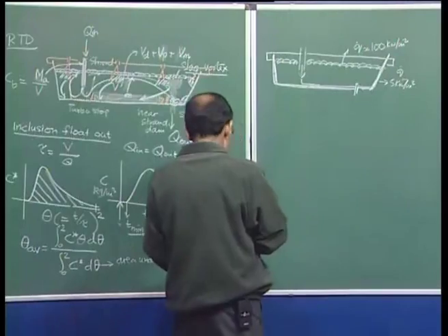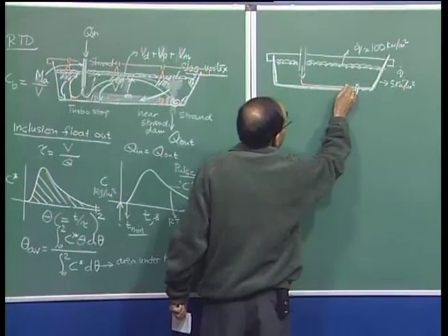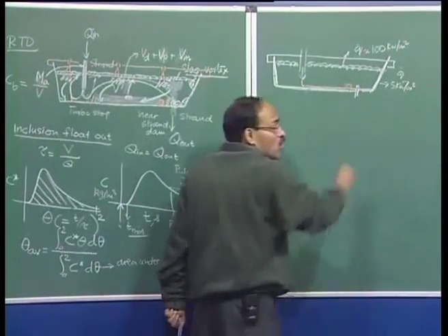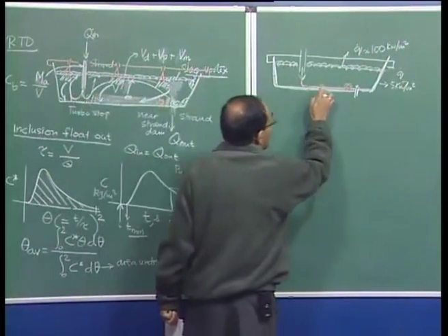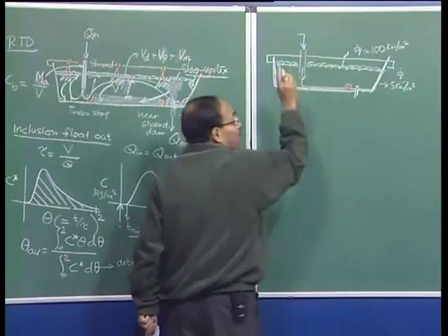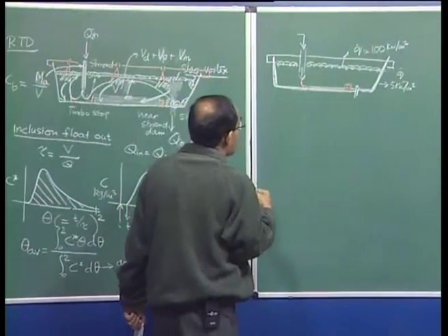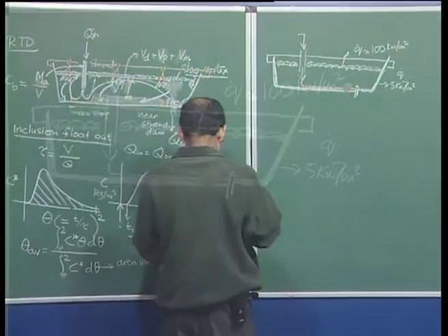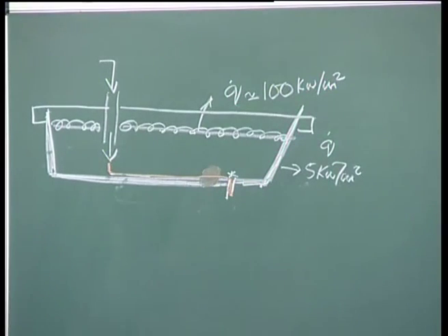So, the material enters the tundish and it flows, and if there is too much of a heat loss, in that case by the time the material goes here, it will lose so much of it that it can actually solidify here, which can create problems. So, to prevent premature solidification, what people do is they pour in molten metal, or the metal in the ladle is significantly overheated, or overheated to some extent at least, to compensate for this heat loss, such that the material can flow uniformly and then can flow out through the exit nozzle itself.